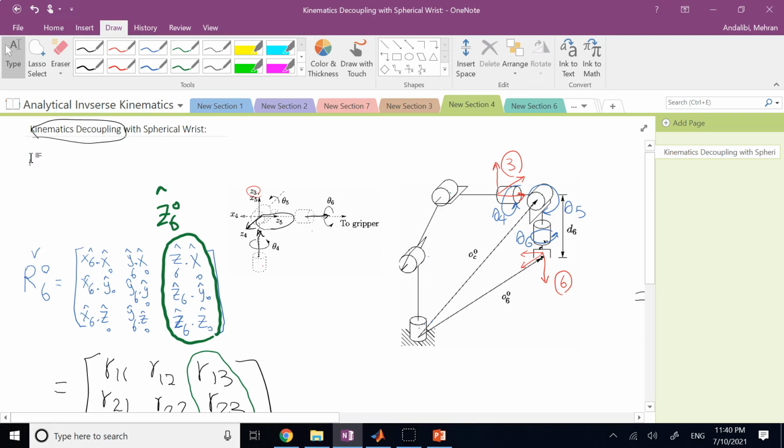The more degrees of freedom you add, the more links you add, the more joints you add, any task we do, forward kinematics, inverse kinematics, later we calculate Jacobian, we calculate forces, torques, anything, control of it, anything you want to do is going to be significantly harder. Okay, and then the other problem is singularity. So if you can design your robot to avoid singularity, try to do so. If not, then you have to come up with a strategy to not be trapped in it.